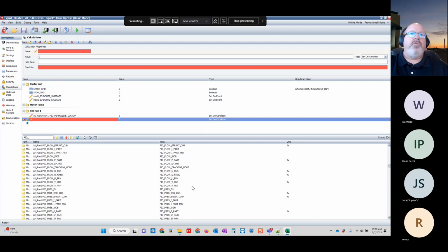Or we could write to the minimum and max values that we would allow it to be. We could say, okay, the control output max limit, or if I'm doing flow control, then my pressure set point is going to be either I'm holding a minimum pressure or a maximum pressure. So let's just write this then.